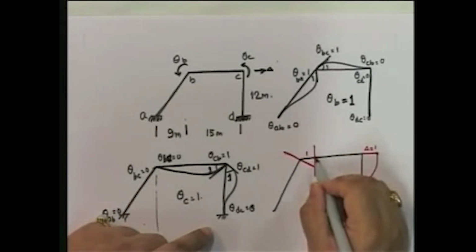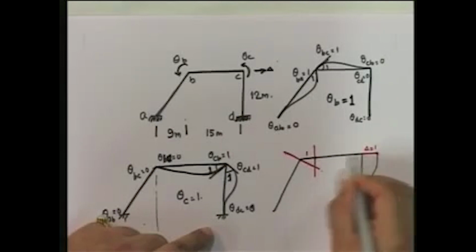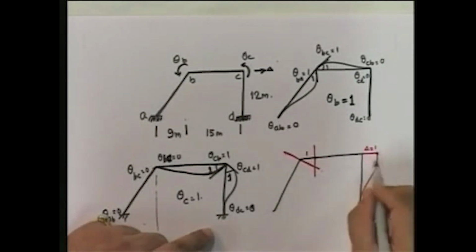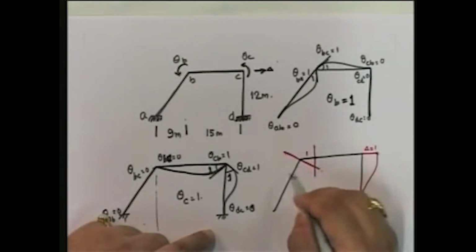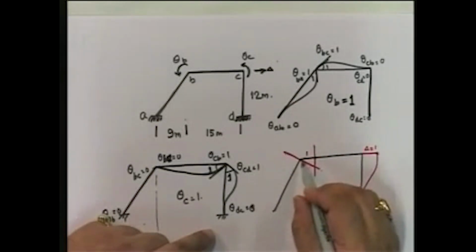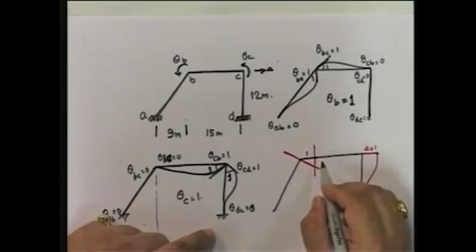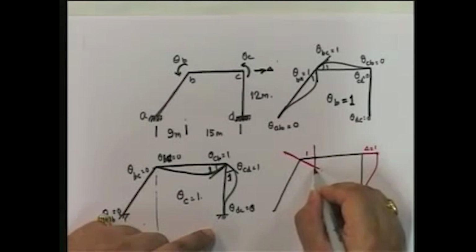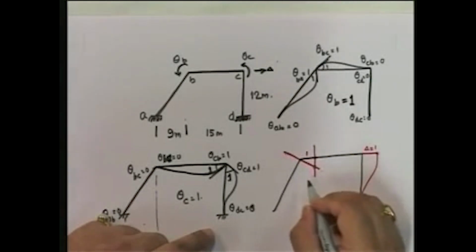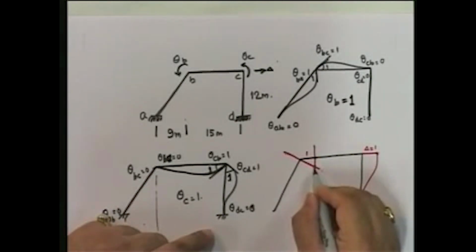So when it has to move, how does it move? Well, it moves perpendicular so that this member does not change length. The whole point here is that since axial rigidity is there, nothing can change its length. So where would the point go? The only way is where these two lines intersect. So this is the point where it would go. So how would it look now?